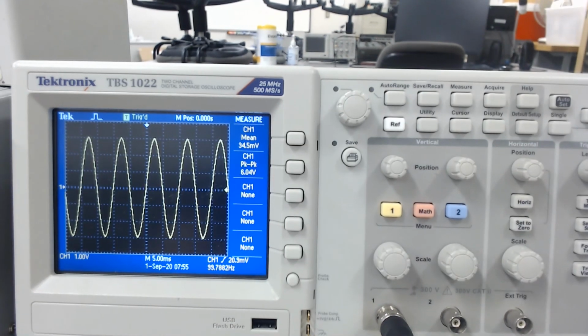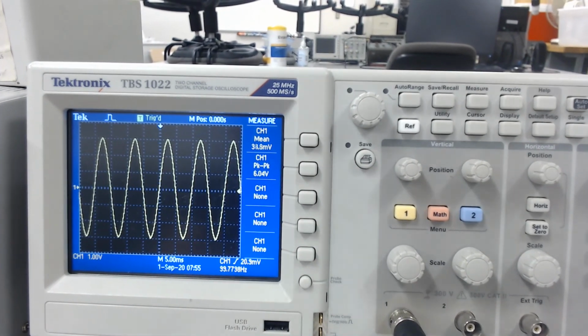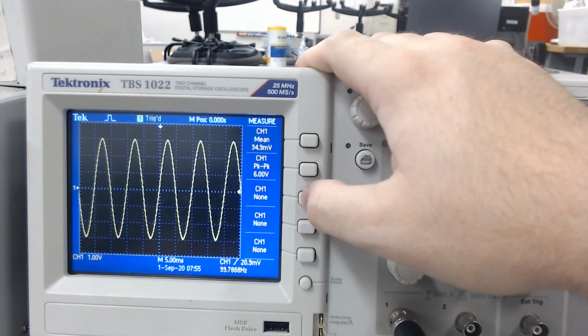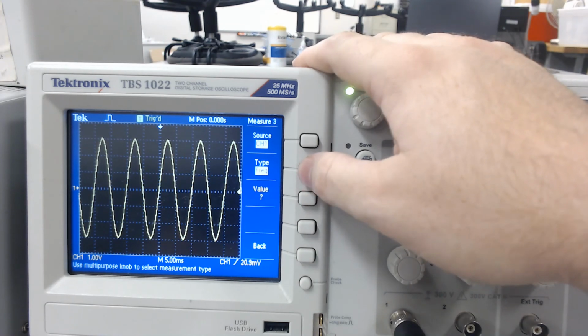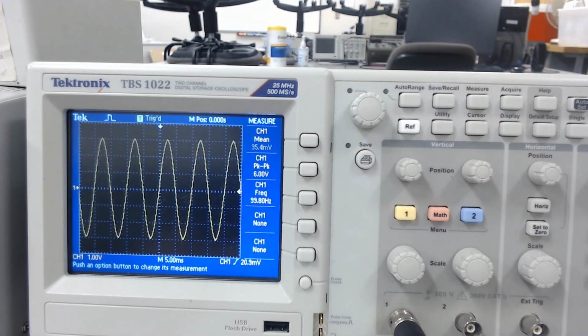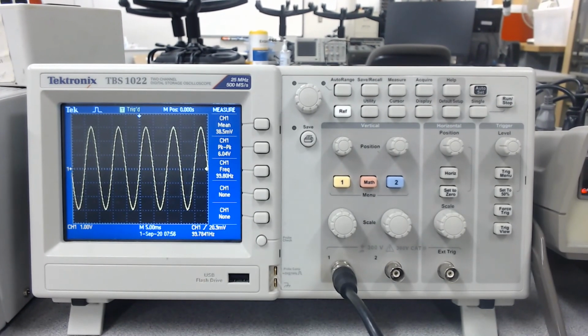So what you're going to want then, obviously, we can change this channel 1 peak, channel 1 nothing, I guess, to the frequency to display it. Our frequency has been decreasing a little bit. That's just an error of the equipment. So this right here is what you would want to submit for the lab report. So this is your oscilloscope. It is showing that your DC offset is roughly 0, your peak to peak is roughly 6, and your frequency is 100 hertz, and it's a sine wave.